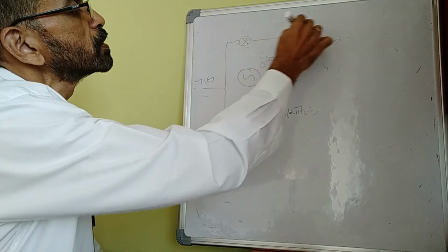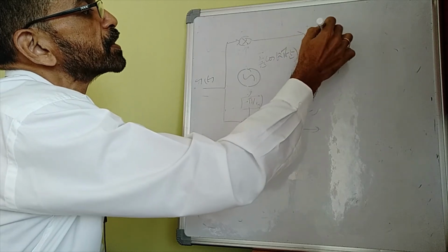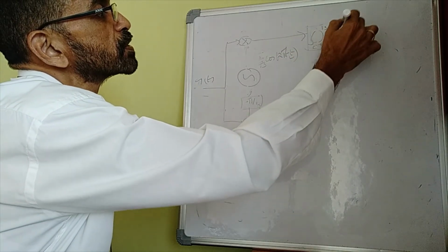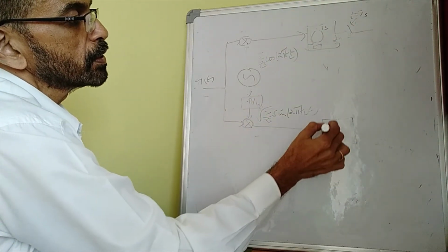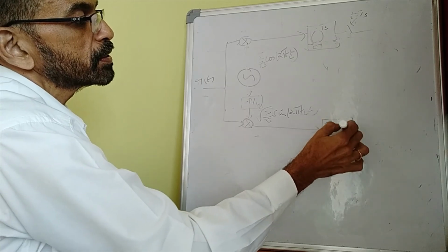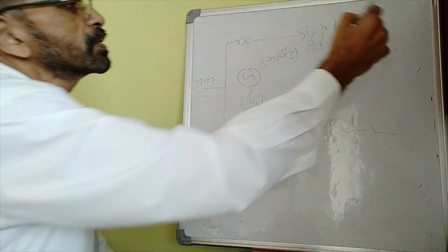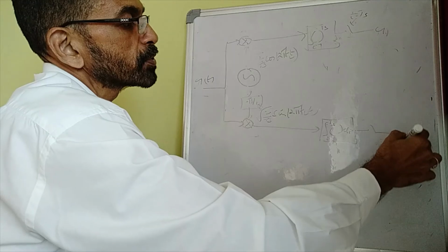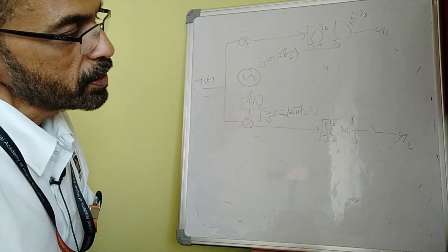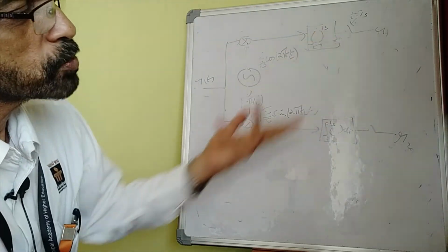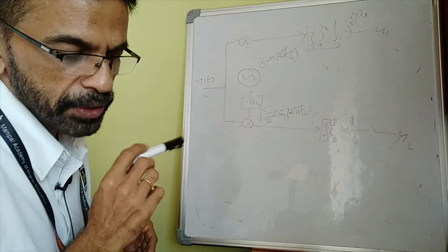Then integrate from 0 to Ts and sample at the end of the integration, in both arms, and you will end up getting R1 and R2, or something proportional to R1 and R2, proportional because I have not considered the splitting of power here. Anyhow, once you have these two, it is possible to go ahead with the decision making, which I will discuss in the next video.